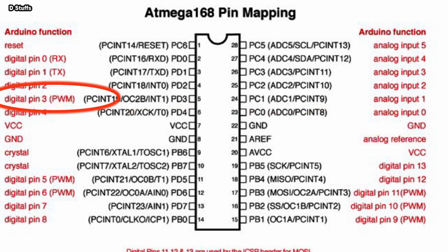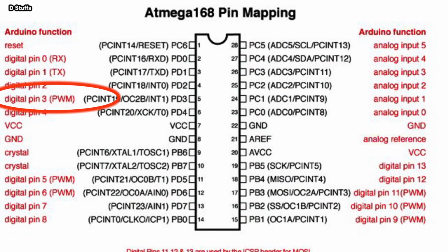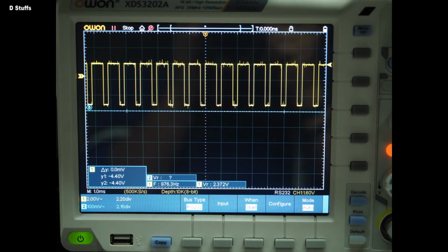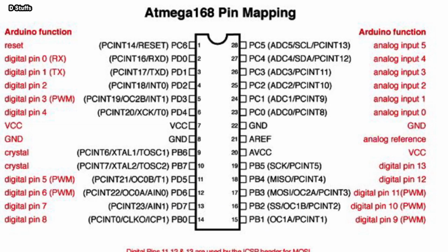Well, you need to think twice, as the alternative function of digital pin 3 is PWM or pulse width modulation, which means you can use it as a general I/O, and why not? But you need to consider your application, whether you need a PWM function or not. But still you can use it, as there are other alternative PWM pins such as digital pin 5 and digital pin 6, which you can use. You get it?